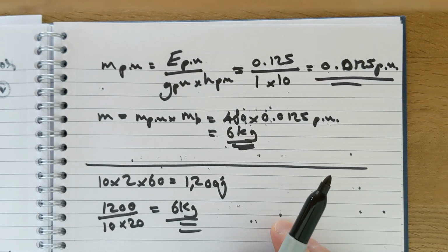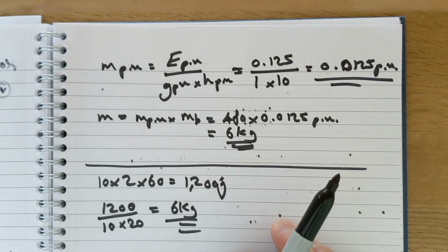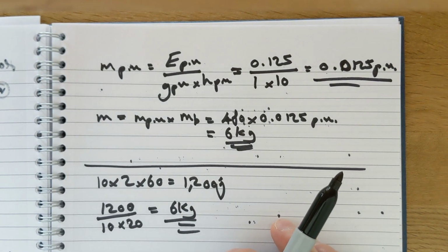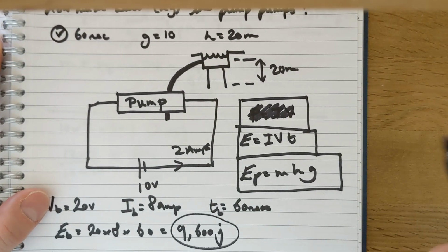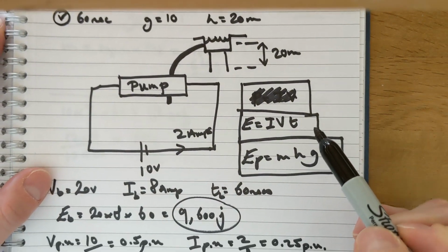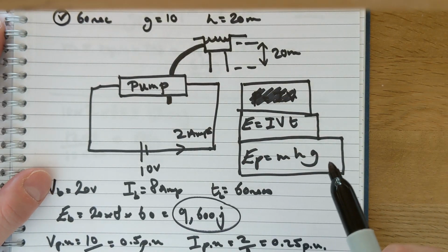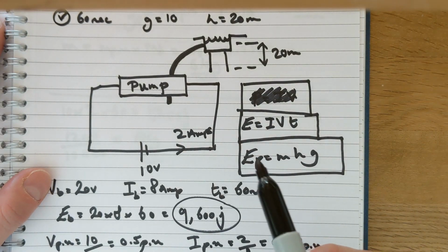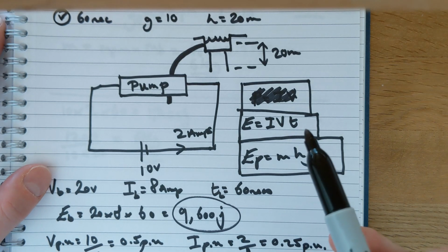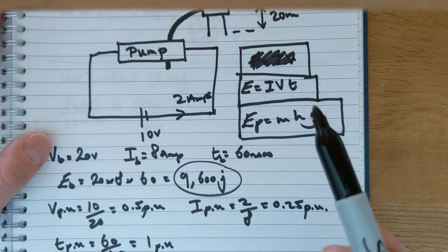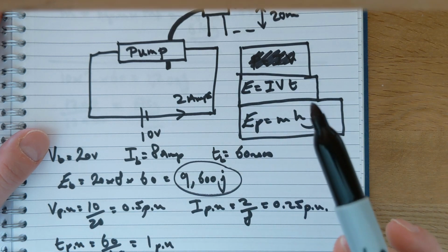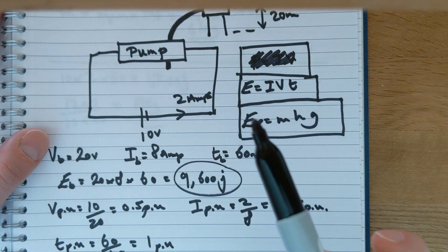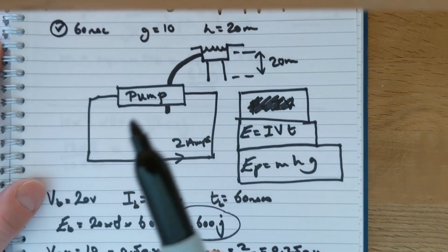Okay, the per unit method is a lot more complicated and laborious, but it proves that the per unit system can be applied to any problem. So in general, if the base values are all related by this, you can just transfer any values for any calculation into per unit, as long as the bases are following the same mathematical rules that are governing the whole system.